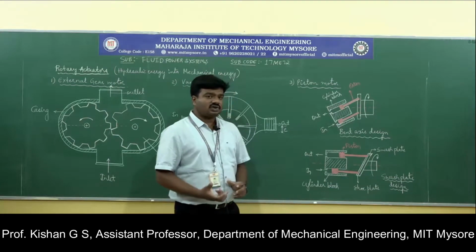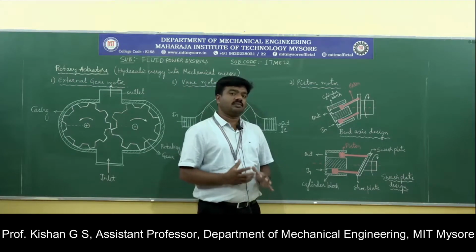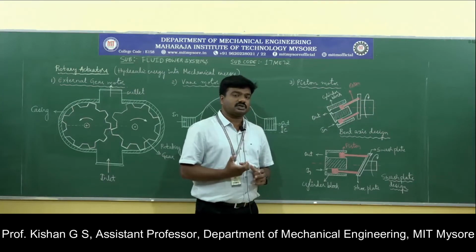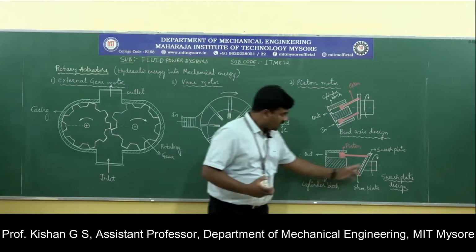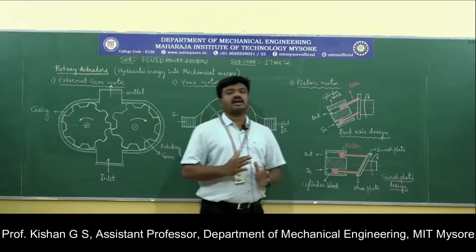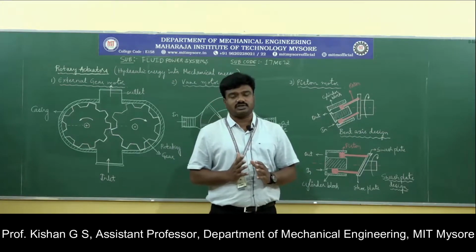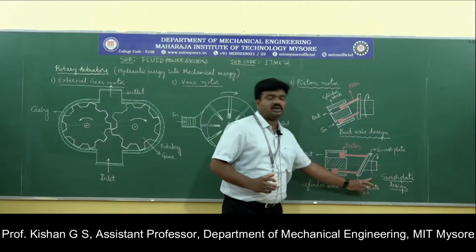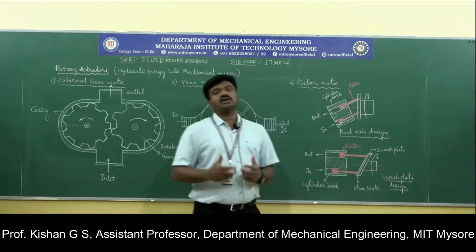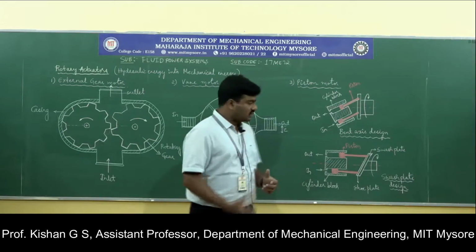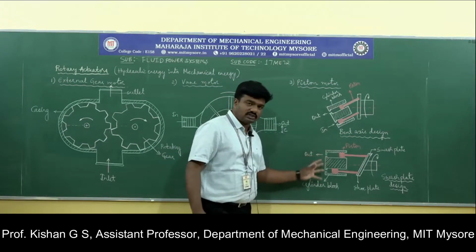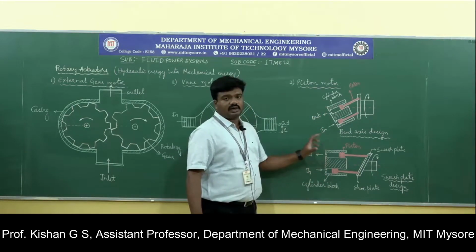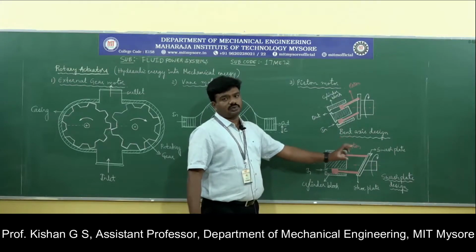Here, instead of giving the inclination to the cylindrical block, we are going to house the pistons in an assembly wherein a swash plate, which is nothing but an inclined plate, is considered as a reference. That inclined plate will be in connection with the drive shaft or the output shaft wherein the torque is going to be extracted. The construction remains the same excluding the orientation of the cylindrical block. Here the cylindrical block will be in line with the drive shaft or the output shaft.